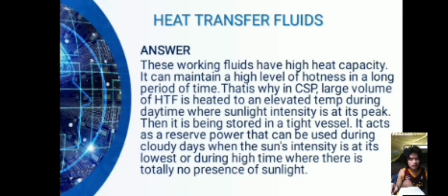That is why in concentrated solar power, a large volume of HTF is heated to an elevated temperature during daytime, where the sunlight intensity is at its peak. Then it is being stored in a tight vessel. It acts as a reserve power that can be used during cloudy days when the sun's intensity is at its lowest, or during nighttime where there is totally no presence of sunlight.